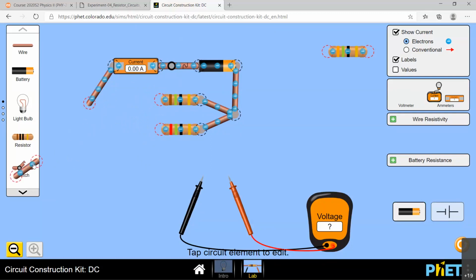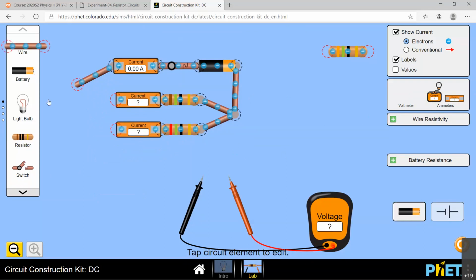If this is a real life experiment, we don't have that many ammeters and voltmeters. We're going to have only one ammeter for each group, right? So if I want to measure current passing through resistor 1, my ammeter should go on that loop, right? That will show you the current passing through that resistor. If I want the current passing through the second resistor, the ammeter should go here, right? So then you can connect these loops again.